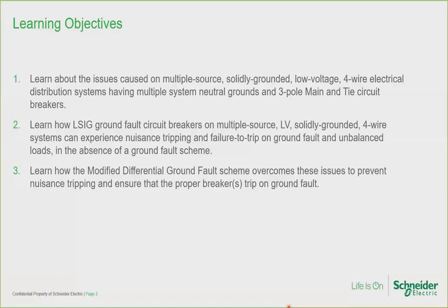You will learn how LSIG ground fault circuit breakers on multiple source 4-wire systems can experience nuisance tripping on unbalanced loads and failure to trip on ground fault in the absence of a ground fault scheme. You will also learn how the modified differential ground fault scheme overcomes these issues to prevent nuisance tripping and ensure that the proper breakers trip on ground fault.